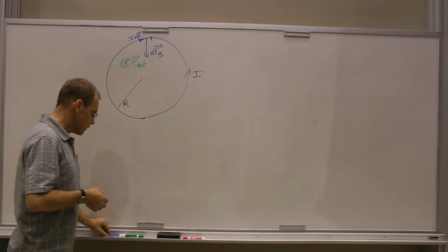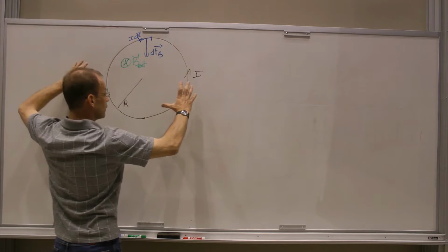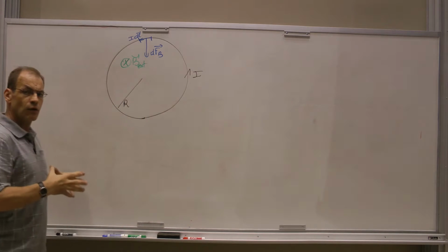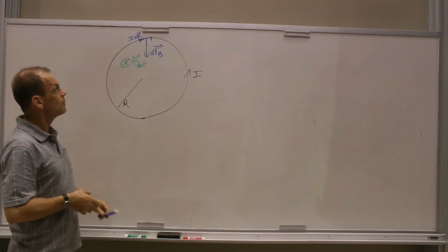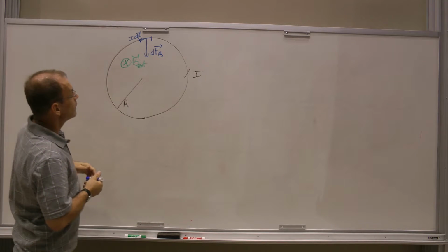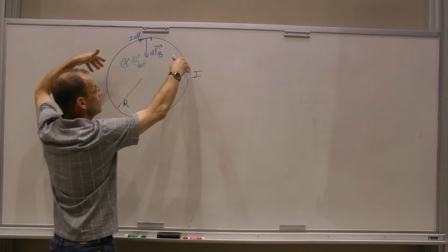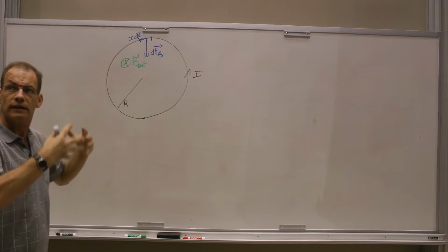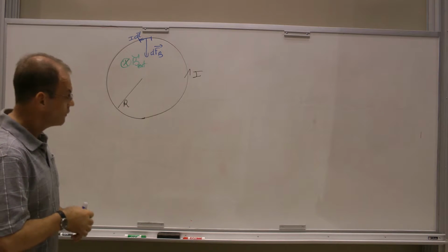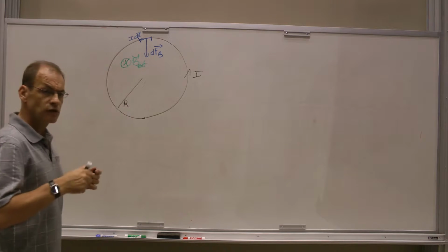But it doesn't mean that we can just ignore this force. The net effect of all these forces is to try to compress the loop, make it reduce its radius. So it is building up tension, or compression rather, in the loop. And I would be interested in figuring out what is the force acting within the loop due to the magnetic forces trying to compress it, reduce its dimension. So it's a classic calculation that you'll see in physics or in engineering.